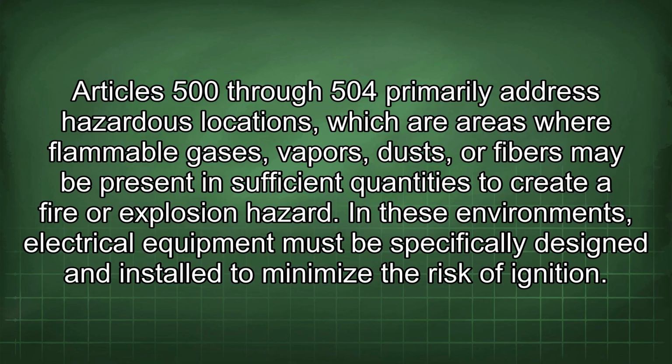Articles 500 through 504 primarily address hazardous locations, which are areas where flammable gases, vapors, dust, or fibers may be present in sufficient quantities to create a fire or explosion hazard. In these environments, electrical equipment must be specifically designed and installed to minimize the risk of ignition.